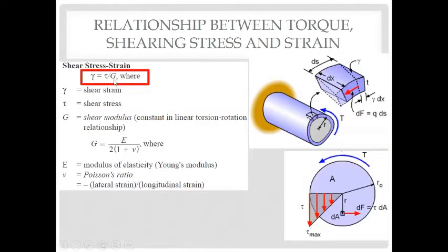But what about the two modulus? We've talked about elastic modulus E and modulus of rigidity G. You can also relate those two with this equation, and this equation is based on elastic theory, right? So if you were in the plastic region, this equation does not apply. So based on elastic theory, we can relate G and E with this relationship here, where this parameter is Poisson's ratio.